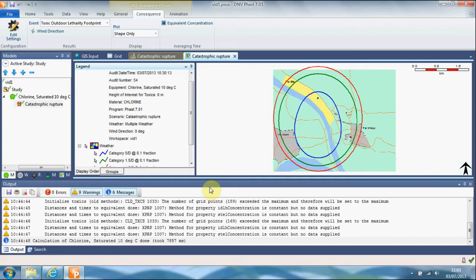There is also the time-varying short pipe scenario, which models the effect of the release on conditions in the vessel and the way that these conditions and the release rate change over time. These time-varying results can be represented either with a single rate or with a series of rates, depending on the options that are set for the scenario. So for this tutorial, we will use the time-varying short pipe scenario, perform an initial run of the discharge calculations, and then we will examine the results and decide on the most appropriate way to represent the behaviour for the rest of the consequence analysis.